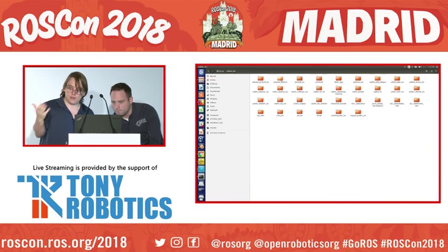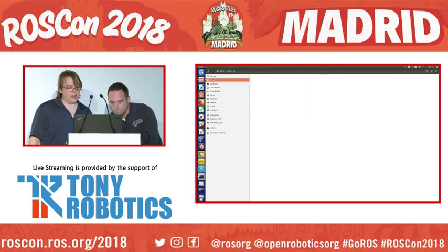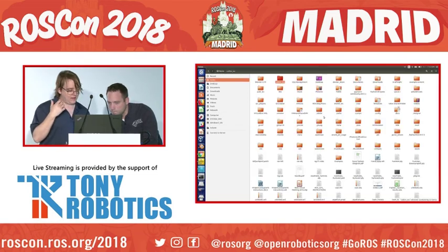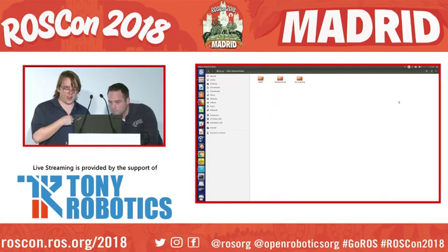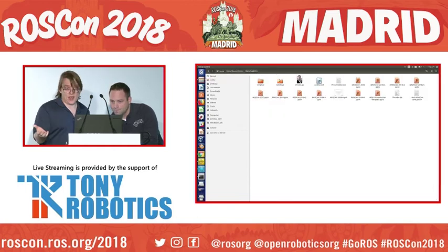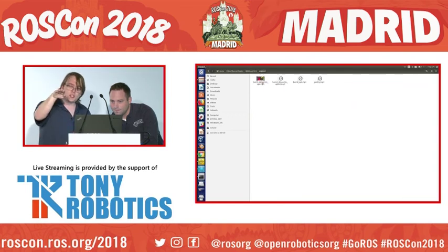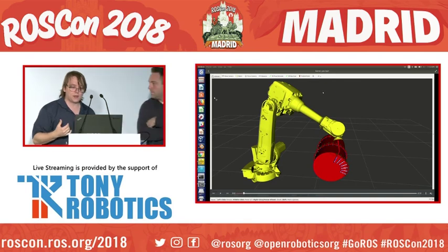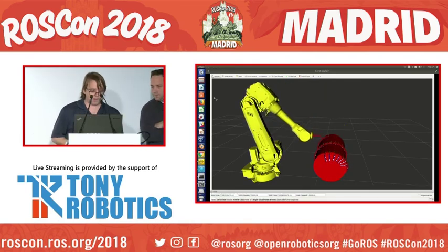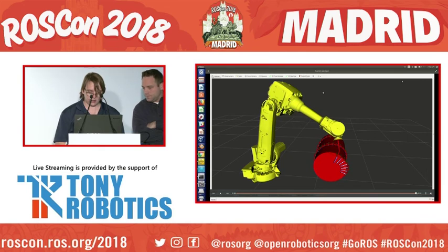But it still has its own problems, right? Discretization doesn't work well in high dimensions, and you end up with little quirks of motion planning. If you only search here, here, and here, your robot path will be moving along, and then you'll see a snap that happens. There are ways to fix it, but that's where doing something like TrajOpt actually makes a lot of sense. So we actually need to go to the next video here.